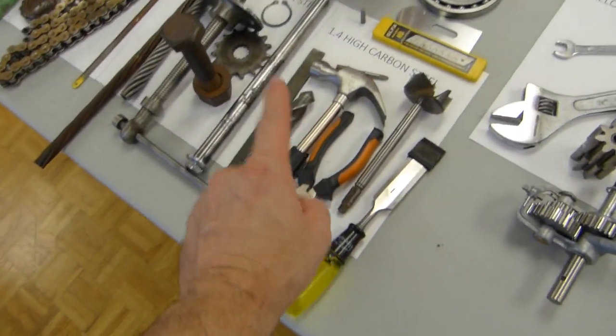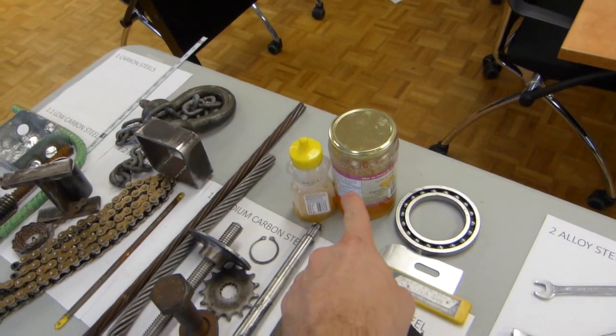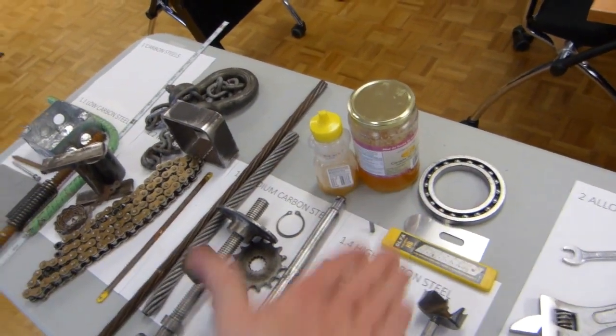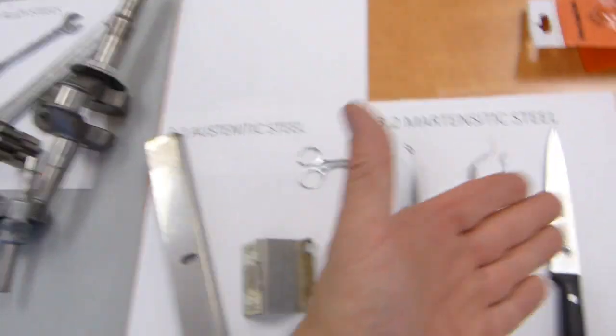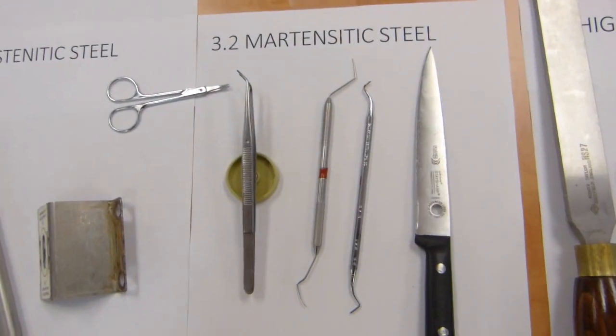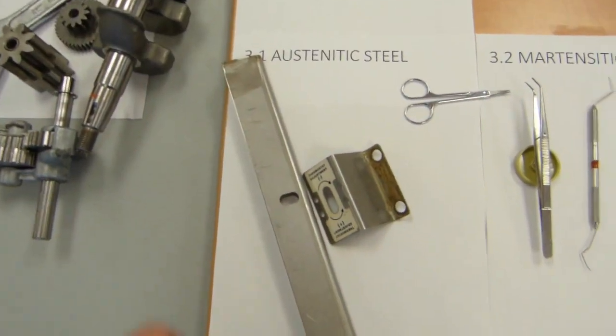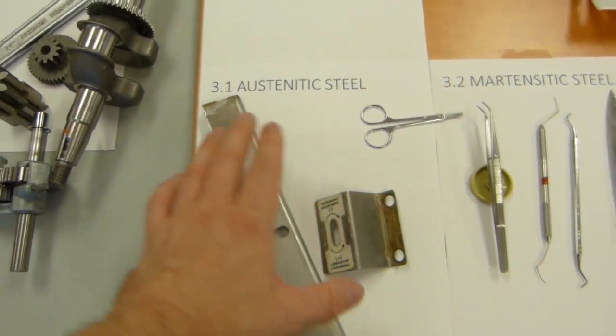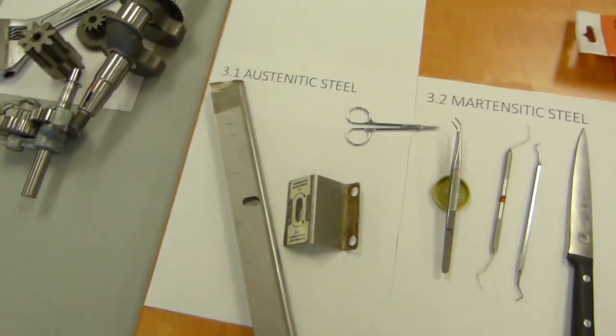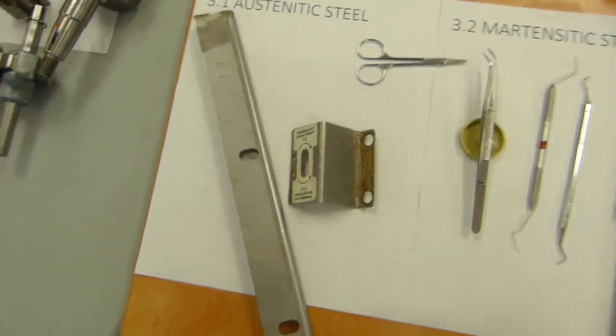High carbon content, unweldable because of the graphite precipitating out. Same story repeating here, alright? So don't even try. The other kind of stuff is highly weldable with the appropriate electrode or filler metal and everything else. So that's all about stainless steels. The next group is coming up over here.